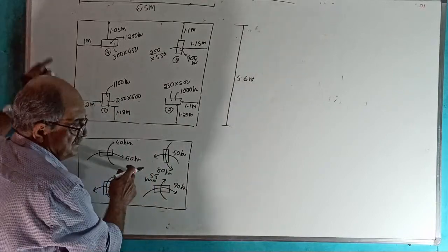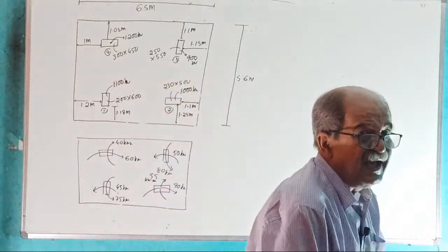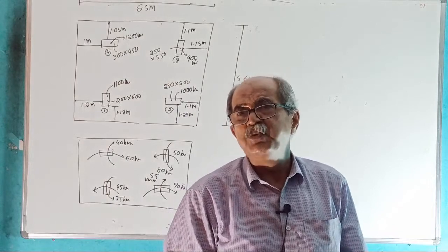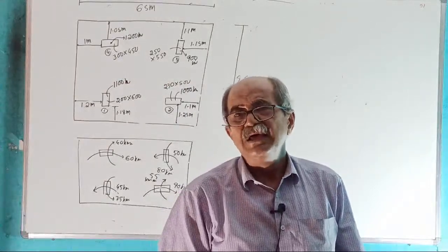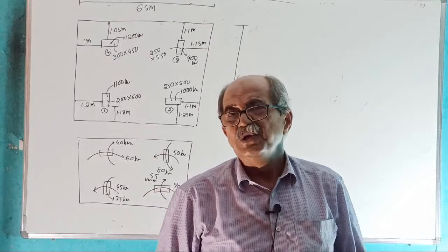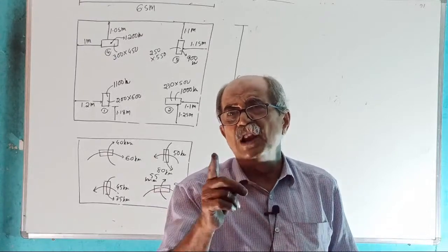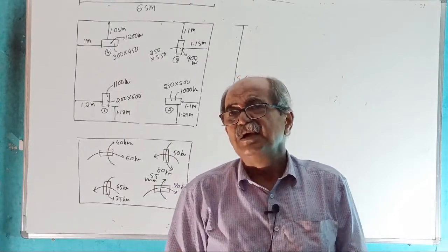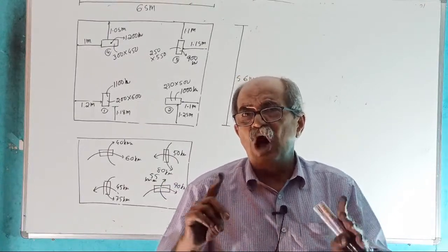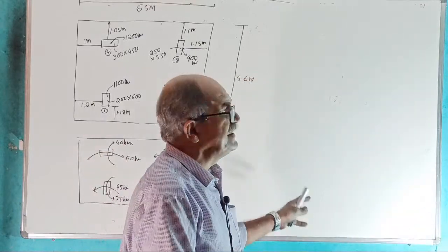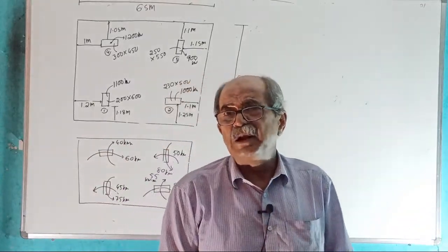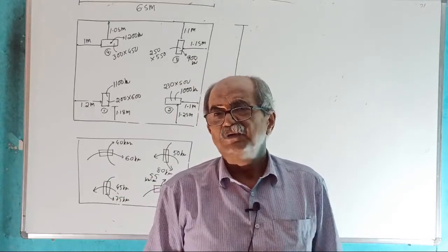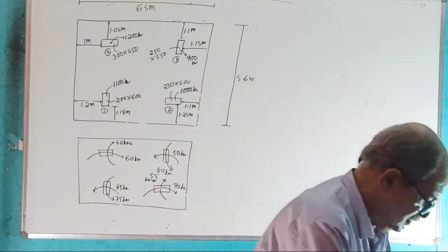Tell me, is this sketch also fully clear? Remember, when you go to rough footing designed by software, you don't have to worry this much. Usually people take total load, fix the area, and increase it by some percentage, provide the area, then software will take care of pressure calculation. It will tell whether pressure exceeds SBC or not. So you don't have to try, but for knowledge purpose I am giving.